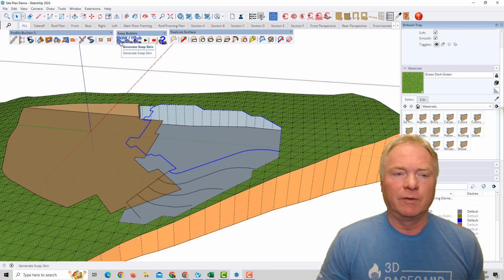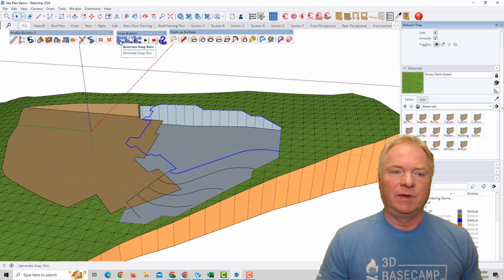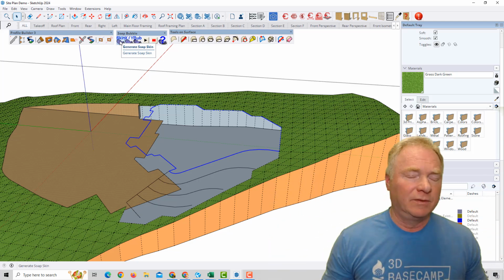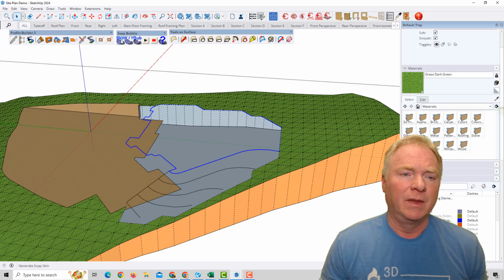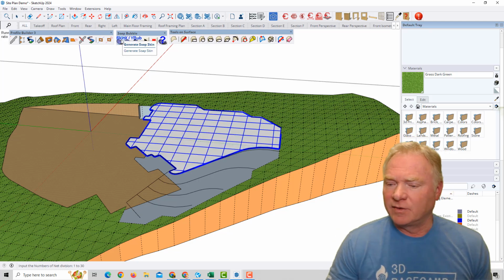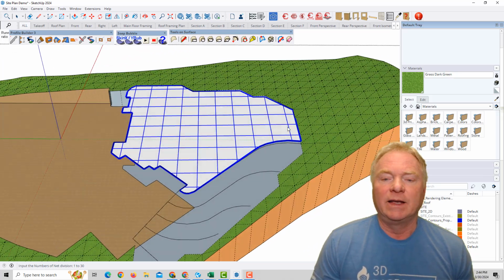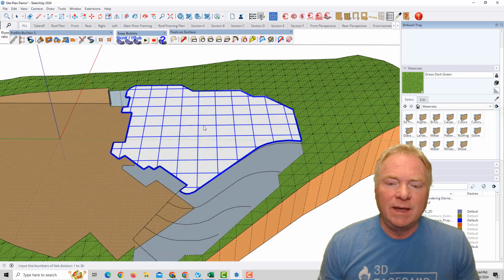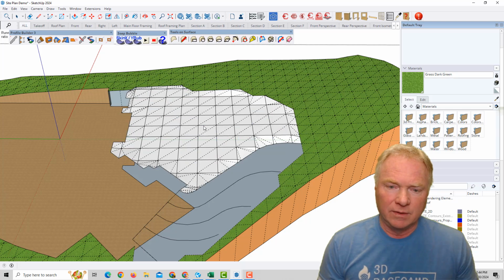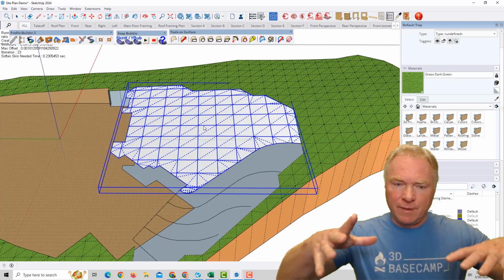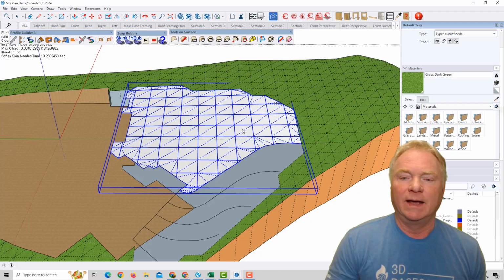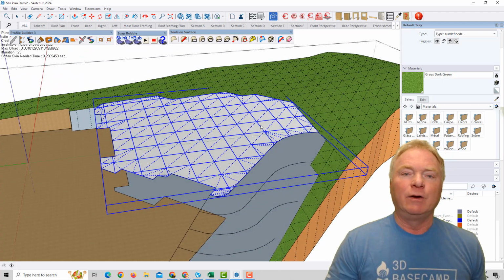Soapskin bubble. So it's this first icon here, generate soap skin. I have no idea where soap came from. Somebody can explain that to me later, but I don't care. So I'm clicking on that, and then it's asking me for the divisions. If you look in the lower right corner in this box, I could change this grid size. To me, it's fine. I'm just going to hit enter, and you see how it just sort of morphed into fitting that shape. Okay, and it's in a group.